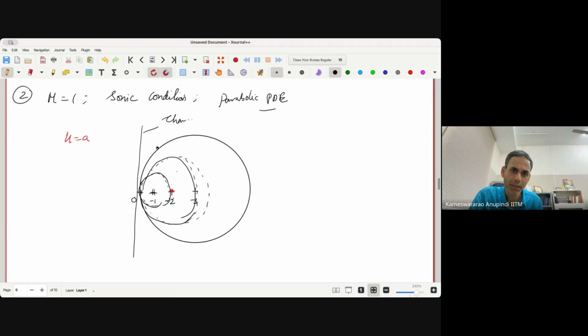And then what you see is that this was emitted at minus 3 seconds, minus 2 seconds, minus 1 second, and this object is now here. The airplane is here, and what you see is that there is no disturbance that is traveling upstream. This region is the quiet region, because the pressure pulse hasn't traveled, and this is the zone of action, as they call it, because this is where the pressure pulse is traveling, and then here this is called the zone of silence.